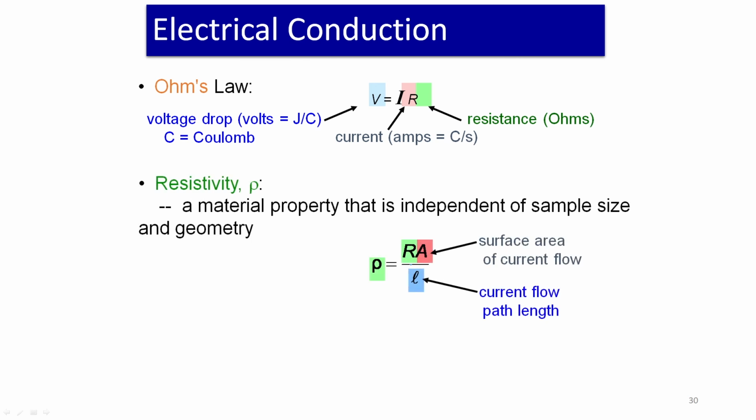And then we can always convert the resistance into a material property. That is called resistivity. So, resistance is not a material property. Resistance depends on many things, like the area and the length of the wire. So, resistivity is rho equal to R into A by L. A is the area and L is the current flow path, that is the length of the wire.